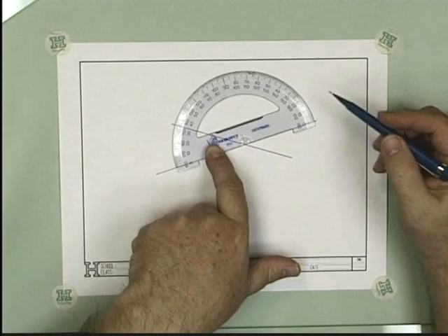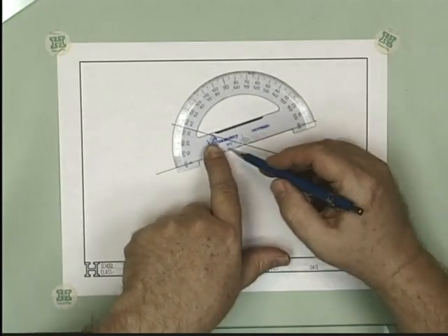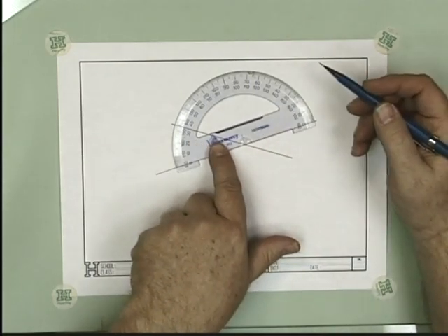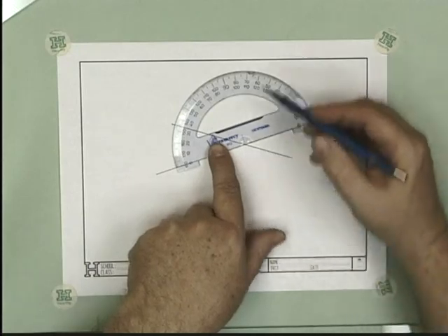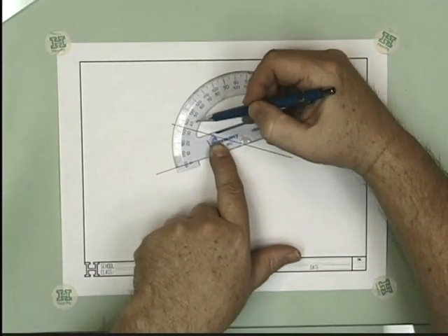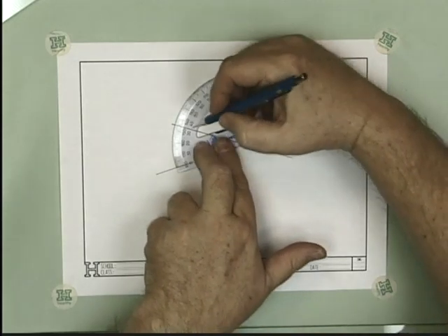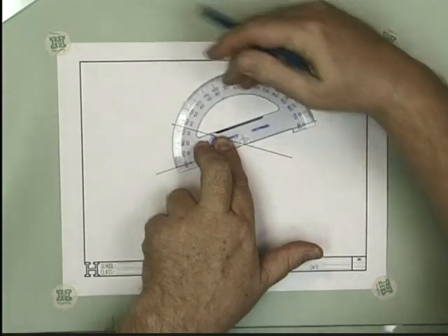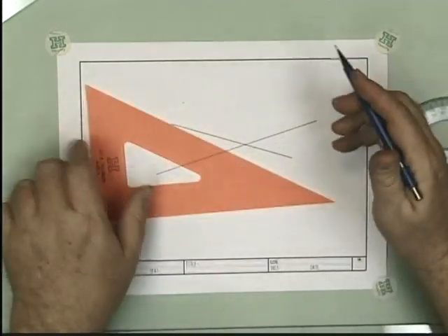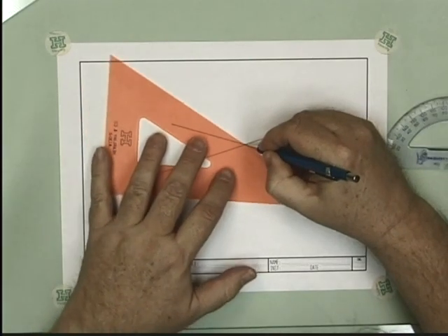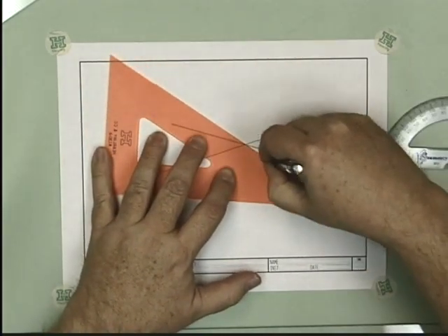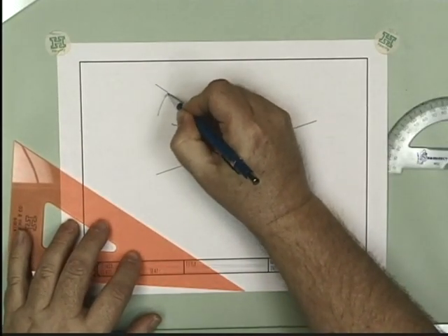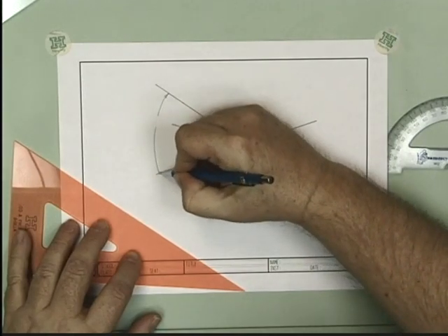You can also use this protractor to construct lines at any angle. Suppose that I wanted to construct a line that was at a 53-degree angle from the starting line. Well, in that case, I'd follow around here, 10, 20, 30, 40. I know this is a little small on the video screen, trust me. 10, 20, 30, 40, 50, 51, 52, 53, and I make a little mark here at 53, and then I take one of my triangles and I carefully draw a line from the intersection point through that little mark I made, and I have a line that's actually a 53-degree angle in this case from my starting line. I'll just sketch in a little dimension there.